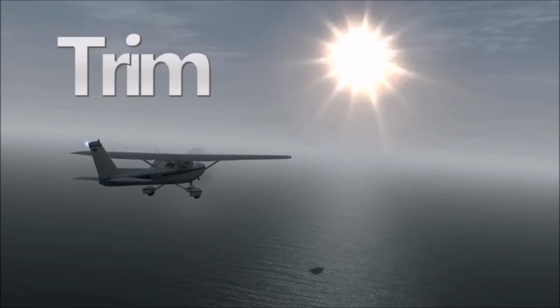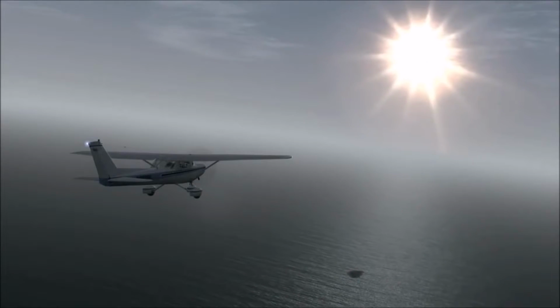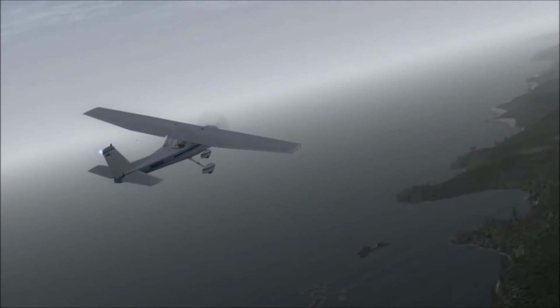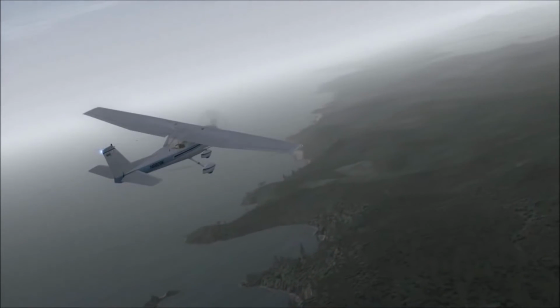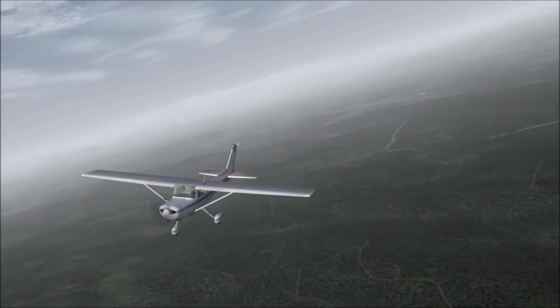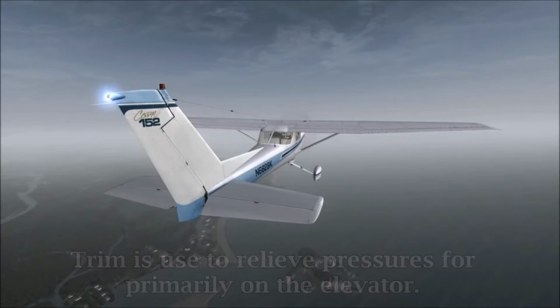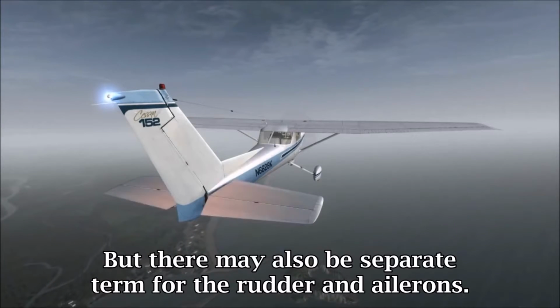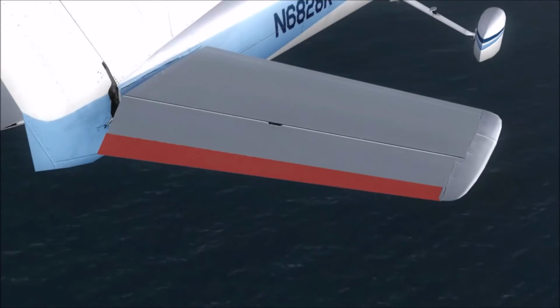Trim. Trimming, in my opinion, is one of the most important skills an aviator can learn. It is going to be quite difficult to tell you why trimming is so important, so for now we'll learn what trim is, why it is important, and how you can expect to use it while flying. Trim is used to relieve pressures for primarily the elevator, but there may also be separate trim for the rudder and ailerons. The trim tab on the elevator can be seen here.